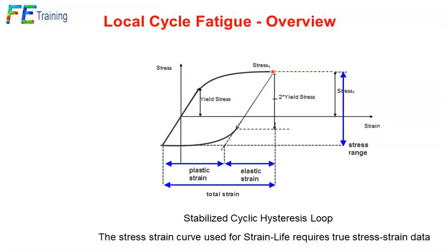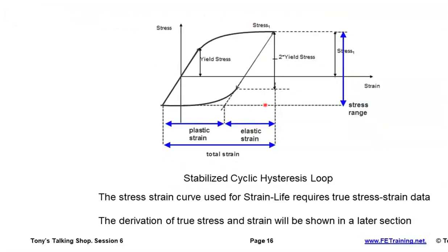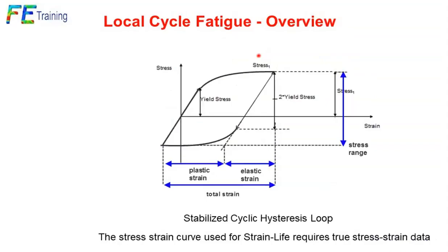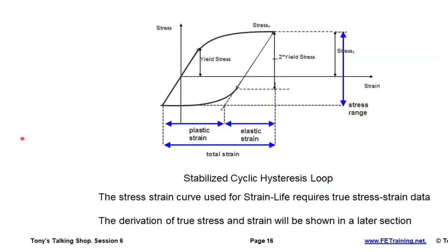So one of the issues is where do we reach that? We can also see that we're including the plastic part. This is the residual plastic strain. We've got the elastic part. We've always got an elastic component playing a role, but we've got ever-increasing amounts of plasticity. So that's what we want to bring in, at least locally. Sometimes we call it the strain-life approach, we call it the EN approach, we call it the low cycle approach. We're saying linearity is just limited to this level. SN-type approaches, high cycle fatigue, are limited to this approach. We want to get over to this point in here because we want to deal with the presence of plasticity.